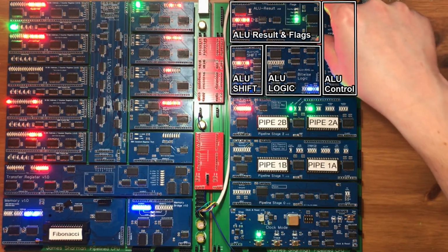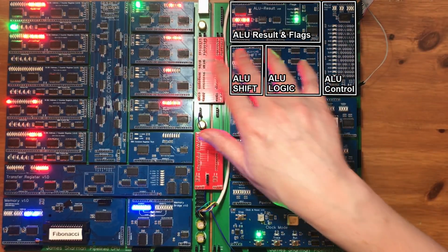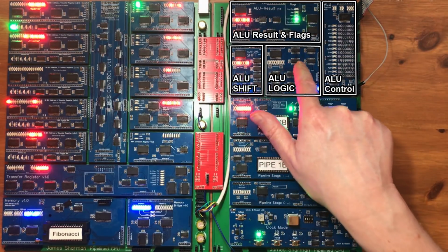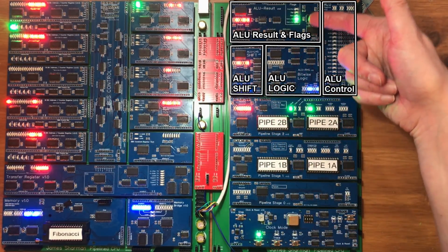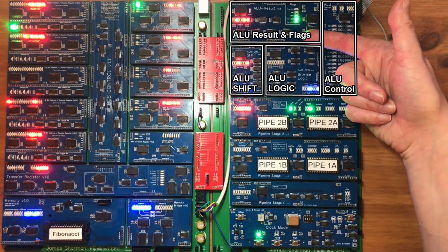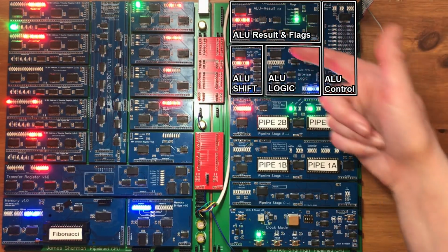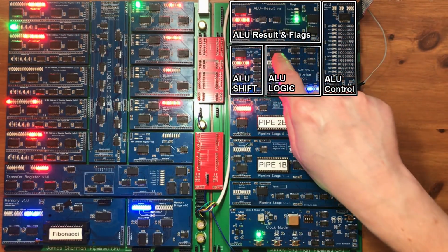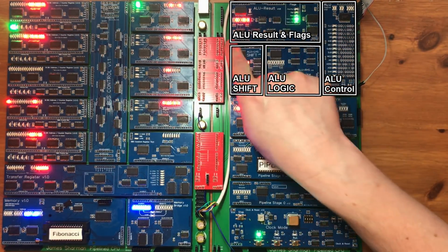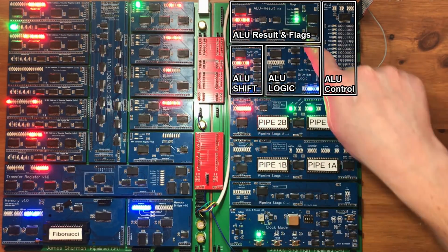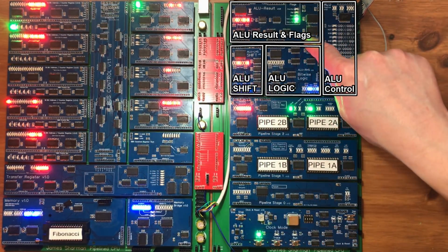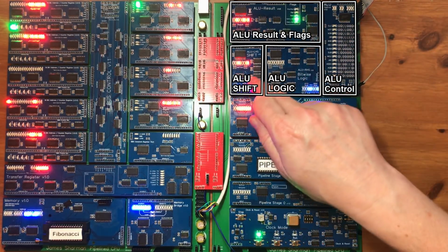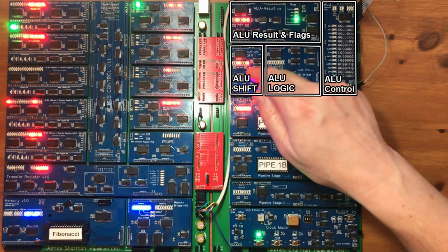So the ALU result is the final operation, and it's an adder. It adds together the outputs from the two early stages, but it also has these 5 flags which it derives from the operation of the data and also uses to manipulate what's going on. A couple of the output bits from the ALU control determine where the carry flag used in the add is coming from, but there are also some derived flags here such as the sign, 0, overflow, and there's a logical carry that comes from the shift unit.